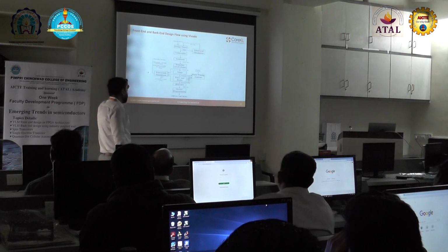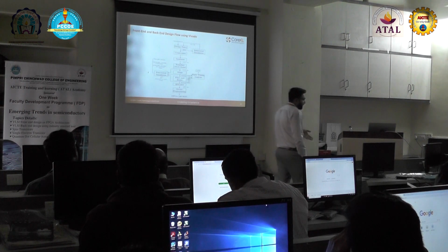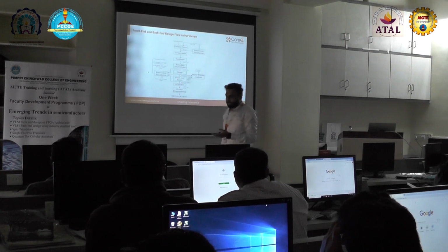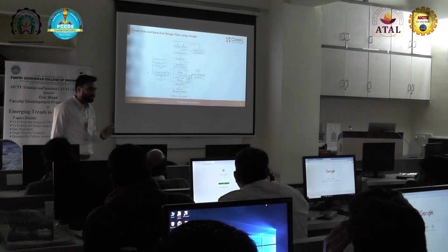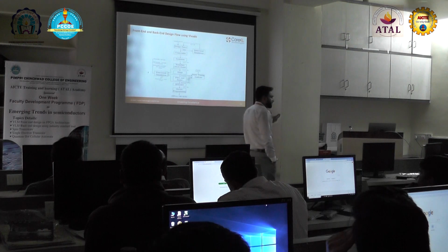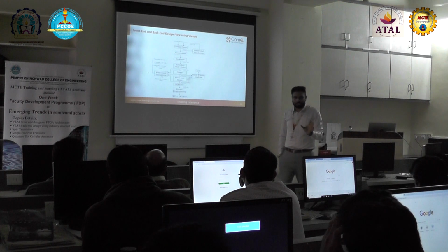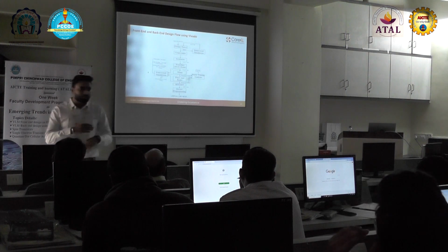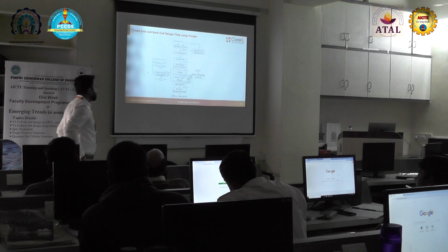After the synthesis is done, the next step is translating the netlist to place and route for optimization. I will tell you in the upcoming slides what operation synthesis technically does. Before synthesis there is something called RTL analysis. Technically what happens after RTL analysis, what happens in synthesis, and what happens after synthesis in implementation, and what is required from the design entries for those processes, we are going to discuss in the next slide.